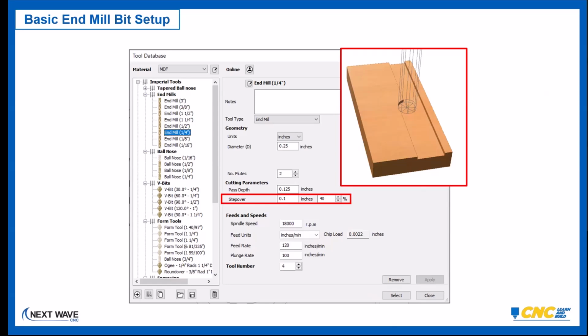The other situation is if you're surfacing a spoil board, then you're typically just taking a light pass. If you're taking such a light pass, and you maybe have a 1 inch or 1.5 inch router bit, end mill, or similar flat cutting bit, in those cases, you could actually step over upwards of 80%. So you get the job done a lot quicker. Again, very comparable to mowing your lawn.